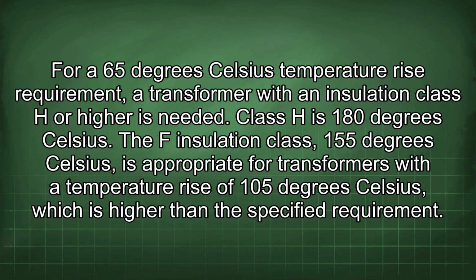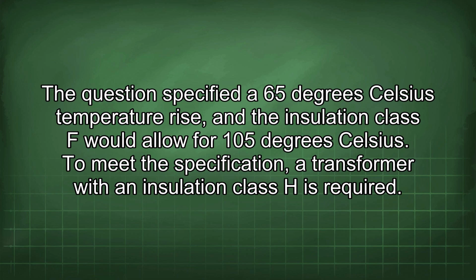The F insulation class, 155 degrees Celsius, is appropriate for transformers with a temperature rise of 105 degrees Celsius, which is higher than the specified requirement. The question specified a 65 degrees Celsius temperature rise, and the insulation class F would allow for 105 degrees Celsius. To meet the specification, a transformer with an insulation class H is required.